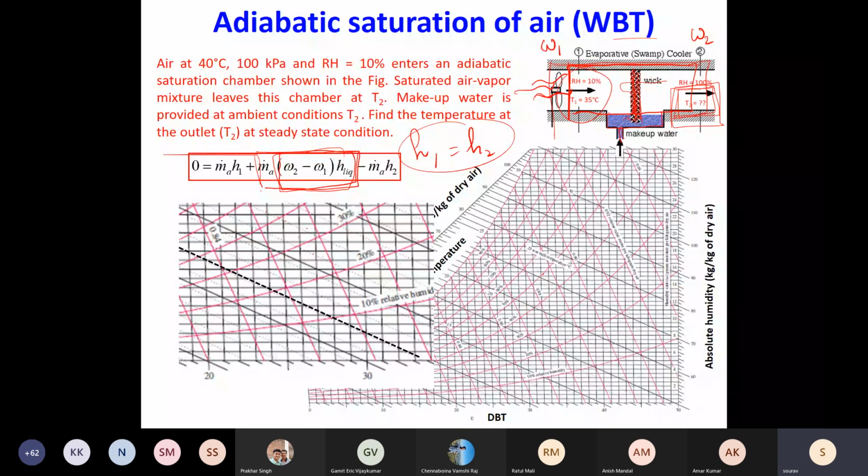The box inside is cooler and the outside air is warmer, so you can have some conduction through the box walls. You will never be able to attain the WBT in your desert cooler. Instead of following the WBT line, you will end up following this flow, with some increase in enthalpy because of conduction from the ambient.